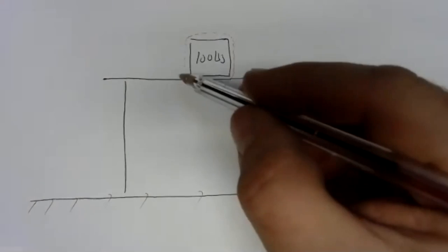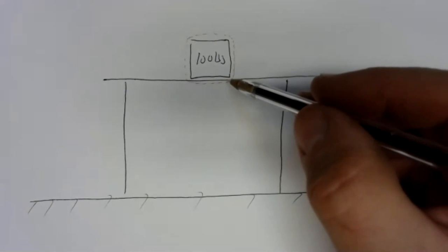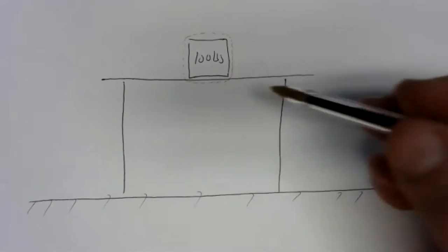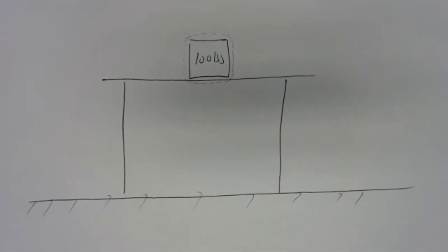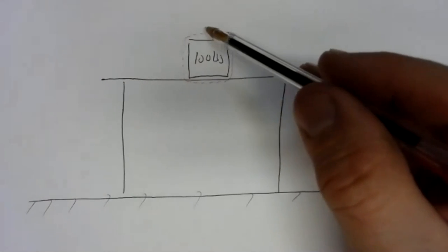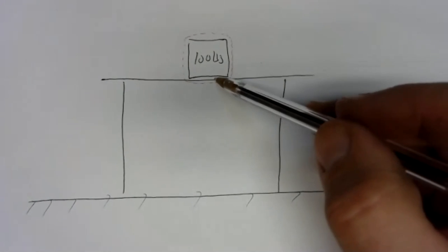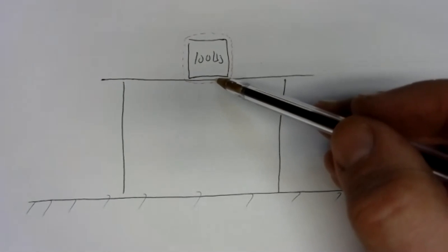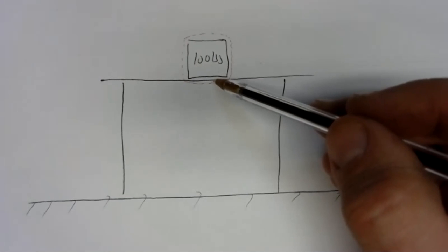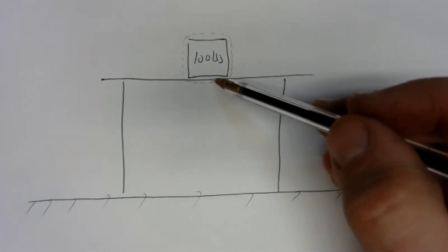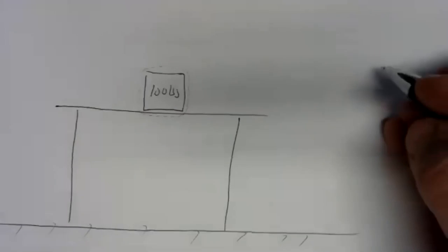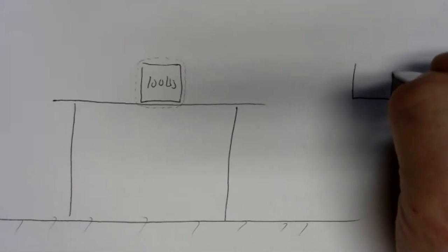Well, if we take that system boundary, that bubble, and we shrink it down as far as we can, certainly if we made that bubble big enough, it could include the table, it could include the house, it could include the planet. We want the smallest bubble that we can get. So we shrink that bubble down until it just includes the object that we're interested in. Anything that we can't get rid of, anything that must cross that boundary or touch that boundary, has to be represented by a force. So if we go off to the side here and we draw our 100-pound box,